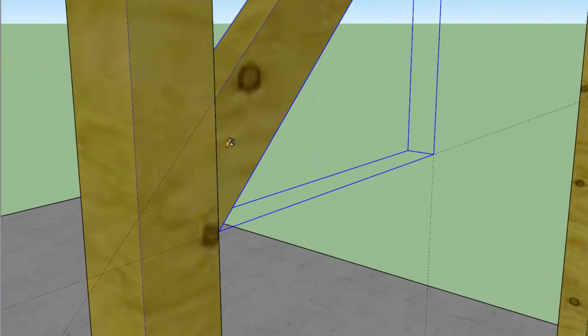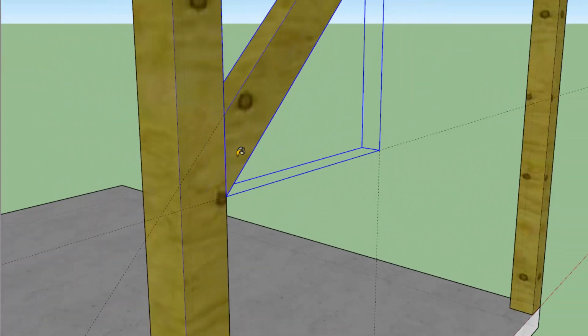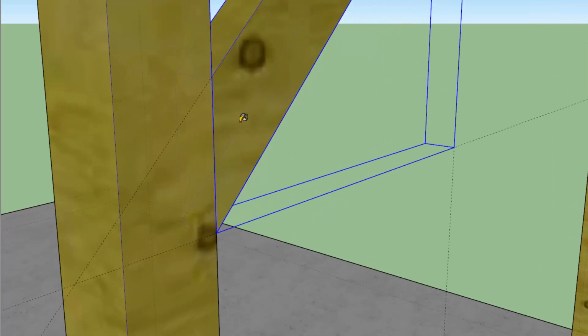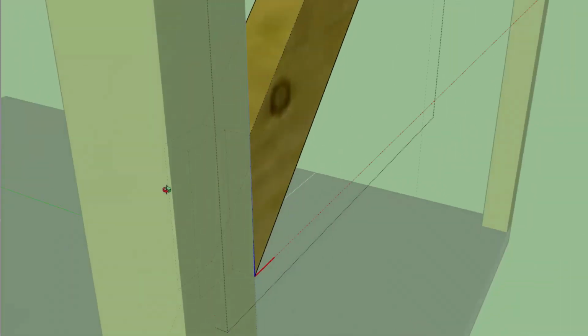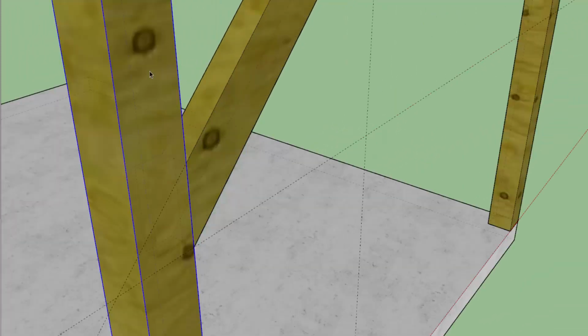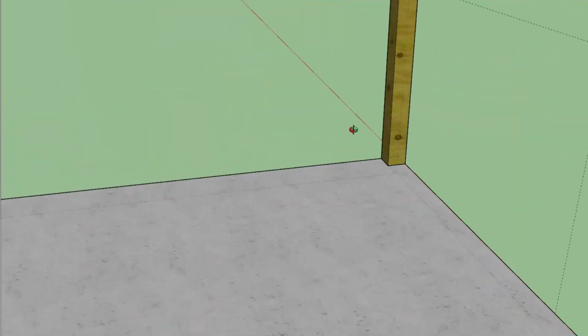Next I want to draw tenons for the knee braces. So I'm going to edit the knee brace. I can just draw a line from the 2 center points. It's a 1.5 inch tenon, which is halfway through a 3-inch member. And I'm going to pull that and make 3-inch tenons. So I type 3 on the keyboard. Now, that's okay, except that, let's hide the post for the moment.